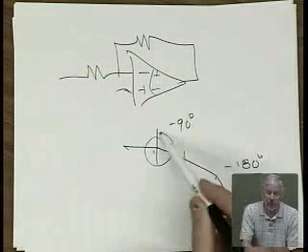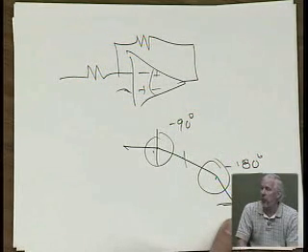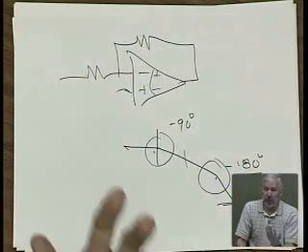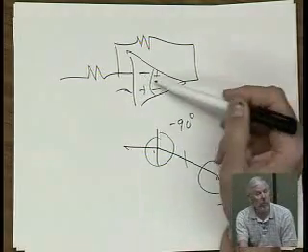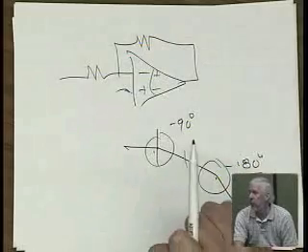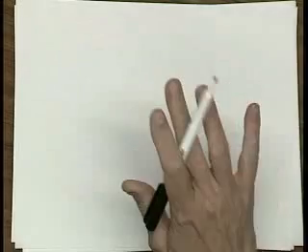So you need to look at where these first two poles are to be able to figure out the stability problem. There'll be more poles out here, but you're already toast, right? Because once you go from negative feedback to positive feedback, you're unstable. So it's the first two poles that give you the trouble. Okie doke. All right.